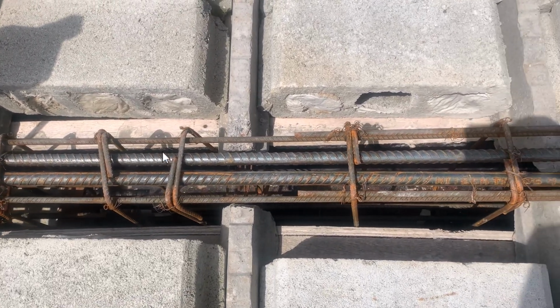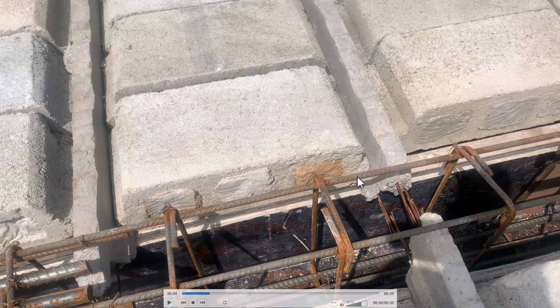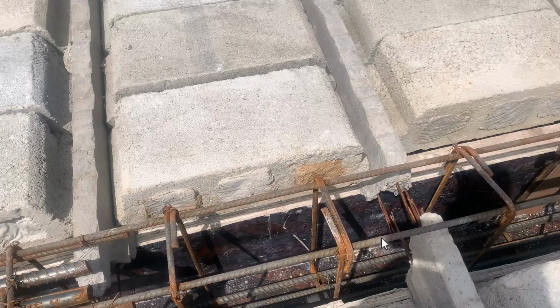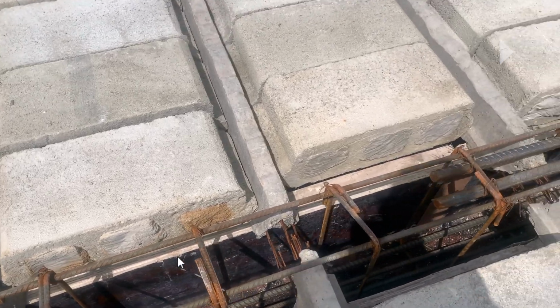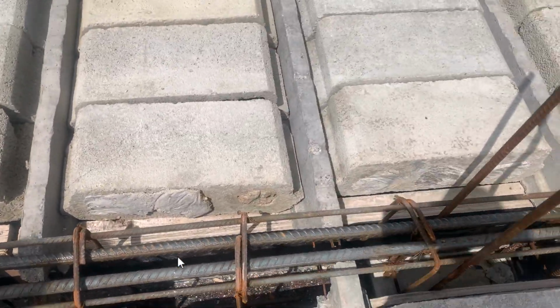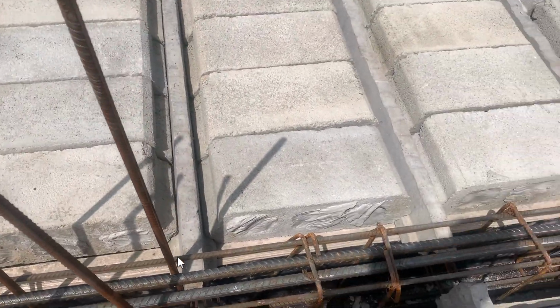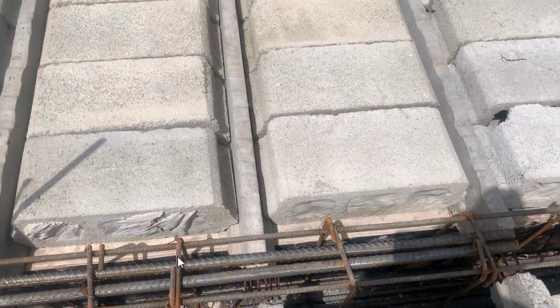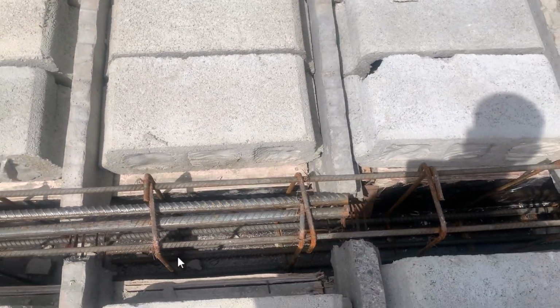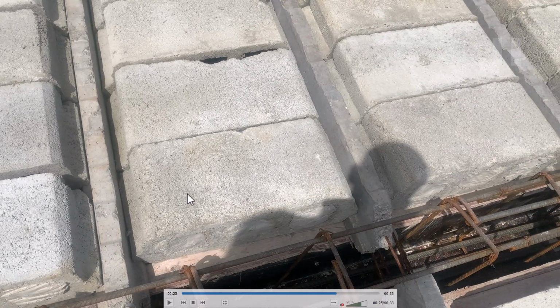And when we move from the column points coming to the midspan, you can see this has been reduced to 2 numbers of y16 because basically we don't have moments at this very point. So we can continue in that regard, getting close to our column. That's the position of our hogging moments. You can see we've also increased the number of reinforcements to 2y25 and 2y16, and we can still maintain that just after the column position, some distance to the right, and we'll get to do more about this when we get to the detailing phase. So this is one of the things that can help you to reduce your number of reinforcement.